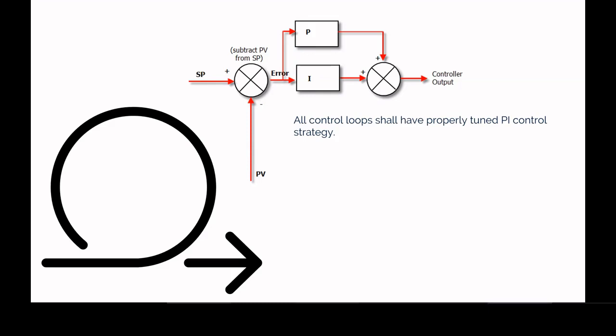And it's a mind thing. So depending on what you're dealing with, it's a different way to think about it. As an example, in space environments, if you're supplying temperature into a space, and you're saying it's 19 degrees and now I need it to be 21 degrees, those 2 or 3 degrees in a space can take quite a long time. So your integral action needs to change there based on that longer time. Whereas if you're controlling the speed of a fan, the moment you add another couple of percentage onto a fan, it's almost instant. So how long does that change take to effect? Well, it's instant. So those calculations are absolutely key to remove what's called hunting or overshooting.